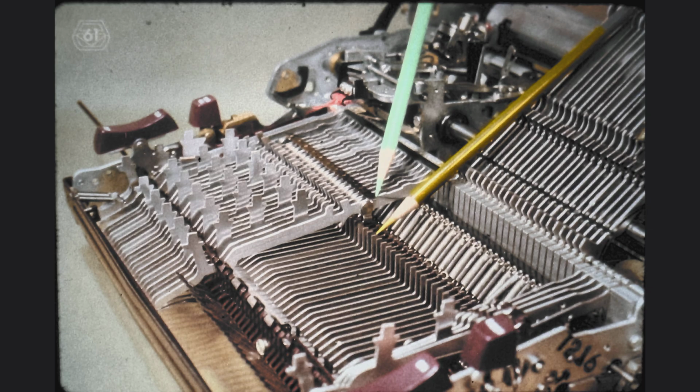An examination of the fulcrum wire will reveal that there is only a clip, or retainer, which holds the fulcrum wire in place. The lug of the interposer, indicated by the green pencil, is pressed downward by the keylever pawl. The filter shaft will then push the interposer toward the front, disengaging it from the keylever pawl while it performs the latch selection. Later in the cycle, when the interposer is no longer held by the interposer latch spring, it is restored in a movement which is simultaneously upward and rearward. This is accomplished by the action of the now clearly visible interposer restoring springs. As a result, the keylever pawl is rotated rearward against the action of the keylever pawl restoring spring.